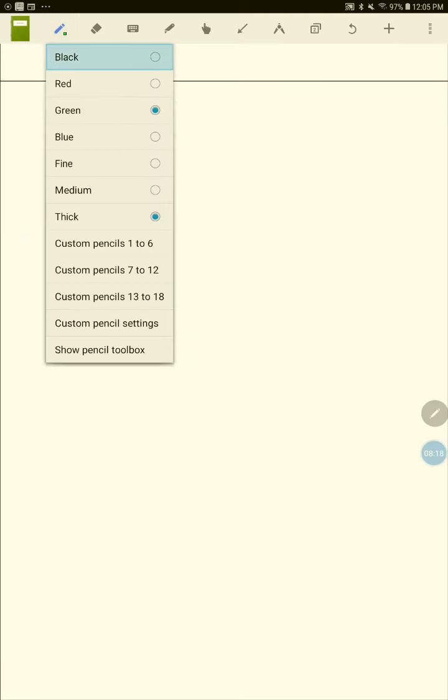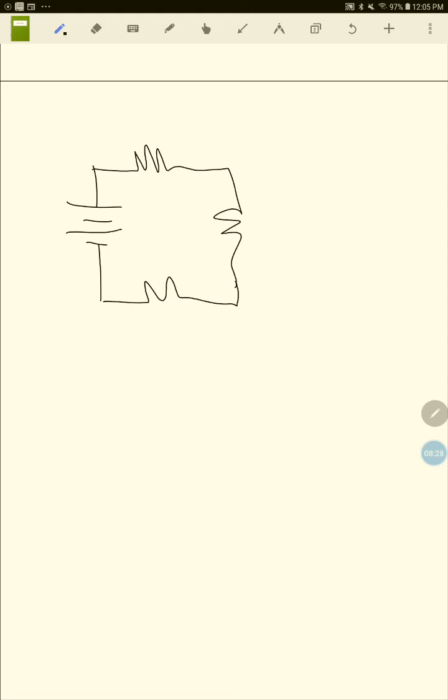Now, the last thing here is what happens if you have a short in a series circuit. So that's kind of the opposite of an open. Here's our series circuit. We've got 3 resistors. We're going to put 4 volts on each one again, just like before. And we'll put 12 volts over here on the battery. 4 times 3 is 12.